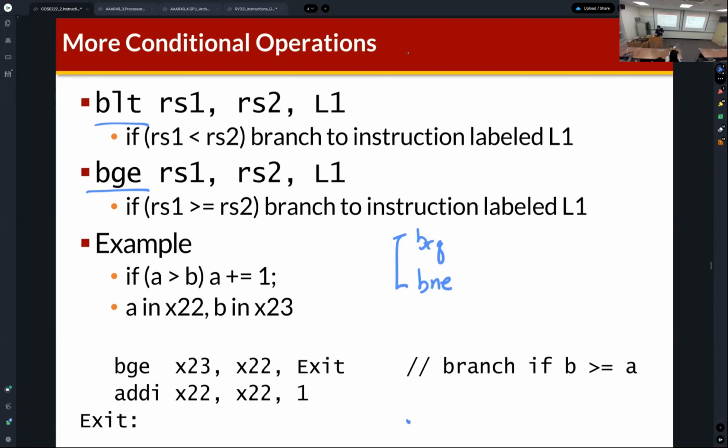Because the data in computer systems is binary data, which means there is 1 1 1 1 1 1 1 1 or 0 0 0 0 0 0 1 1. Then how can you check the equality? You can check the equality of this binary data by checking the equality of each bit. And it's very simple because we can use an exclusive OR gate.